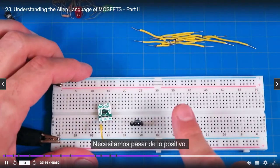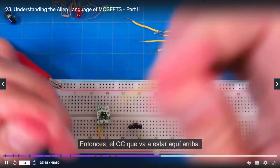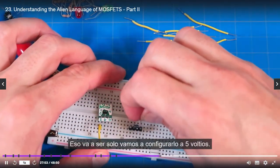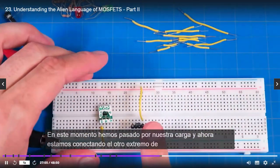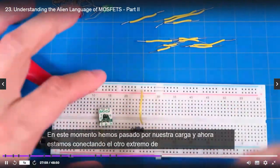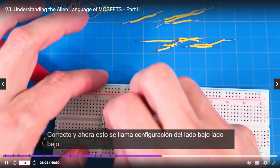So what do we need? We need to go from the positive, V sub CC, which is going to be up here, and we're going to set it at 5 volts. Now we've gone through our load, and now we're connecting the other end of the load to the drain. This is called a low side configuration.